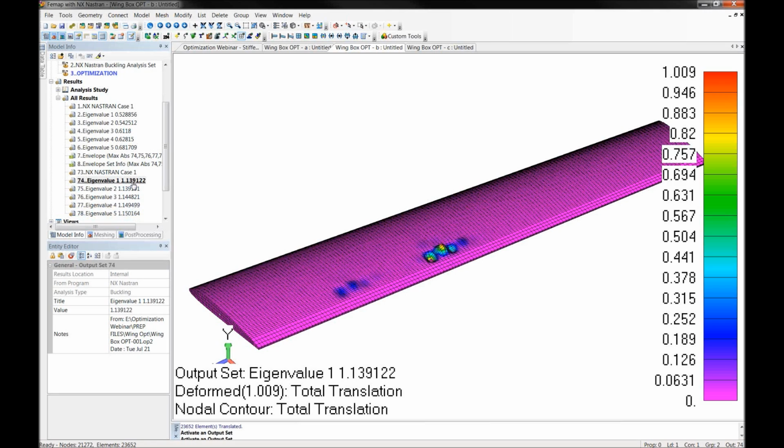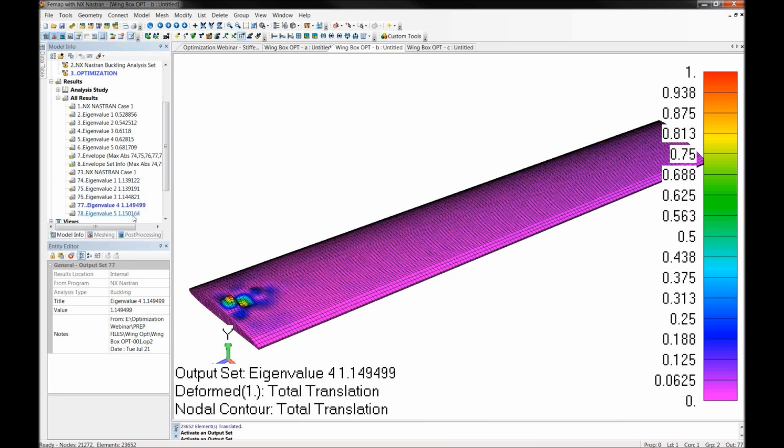So I set it to 2% rather than 0.1%. So I loosened it up to give it a little more flexibility, a little more range to find an optimal solution. And that does help it converge, but obviously you have to be aware of what your tolerance is. So we have modes all over the place that are relative to 1.15.